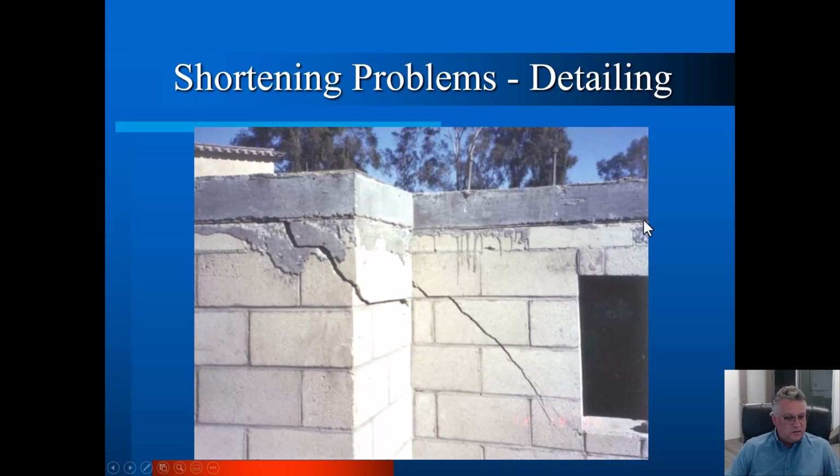Masonite is a material, if you've ever bought cheap IKEA furniture, that flimsy piece of wood, cardboardish thing on the back of your bookshelves. That's what masonite is, and it works better for building material, I think, than it does for the back of a bookshelf. Anyway, we use 2 pieces of those, and the slab tends to slide really well along those 2 pieces of masonite board. But it doesn't if the engineer above puts anchor bolts right through all of the system.